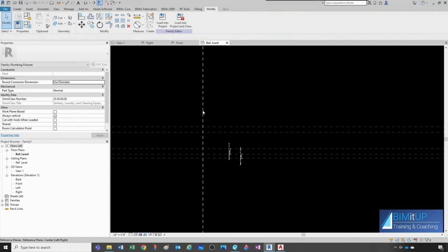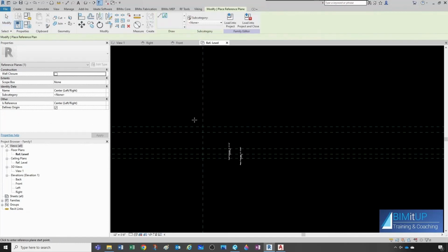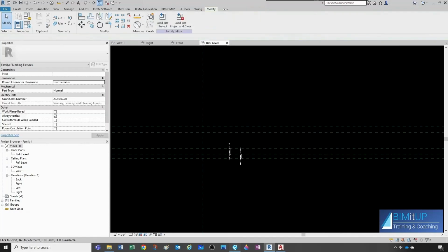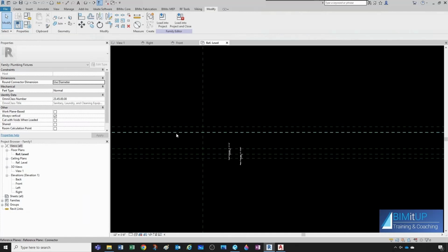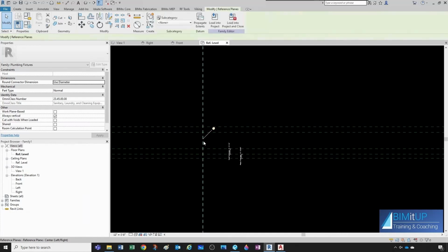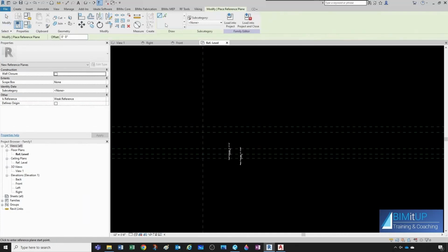And now we need a couple of planes in this direction to limit our width, right? So create similar, and let's see. That's gonna be 5 inches total. So I'm just gonna give 2 inches for now, and then I'm gonna associate the parameter and have that parameter be 5 inches to make sure it's flexing fine. So click here, create similar, pick planes, 2 inches to this side, and then 2 inches to this side.